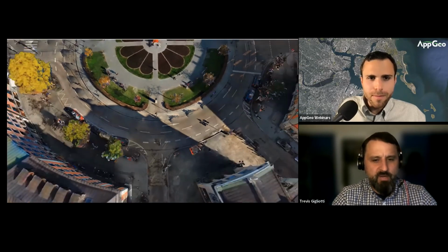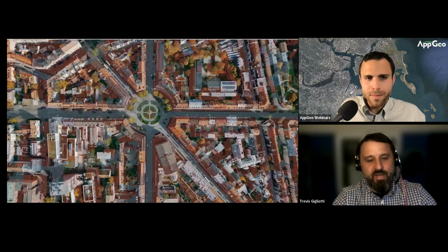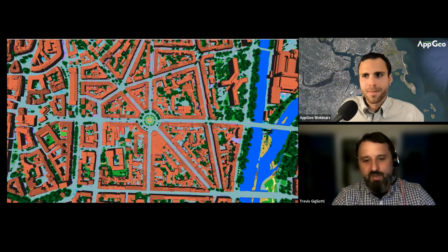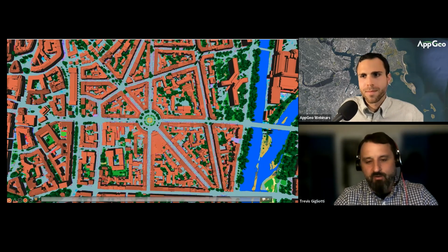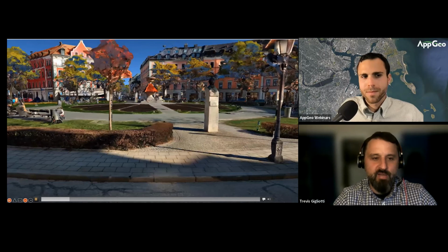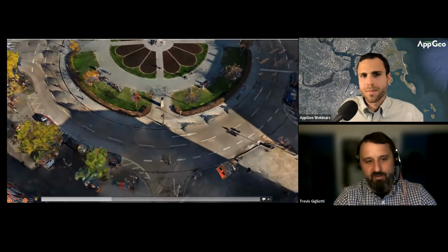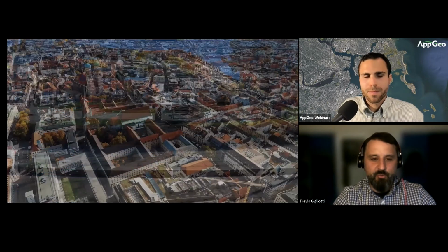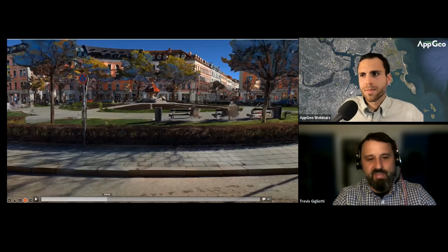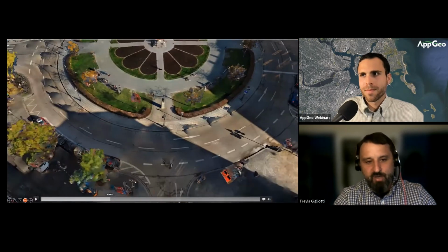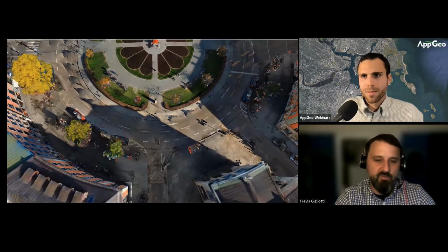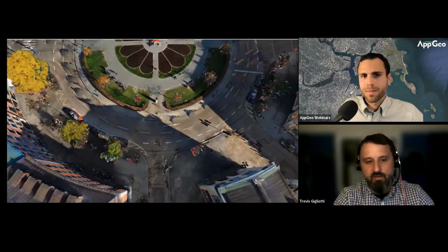Yeah, so the beautiful thing about here, like I mentioned before, Aaron, since we're getting the geometry right, we're able to integrate with further sensors and data sets, right? So we started off there showing actually a mobile LiDAR collect, and we're able to integrate that with our aerial products as well. So we're able to get an accurate representation of the ground scene and then extend that up to fill in the gaps or the holes with the aerial data products. But we couldn't do that if we didn't have the geometry right, which again goes back to the benefits of the LiDAR data that we're collecting.